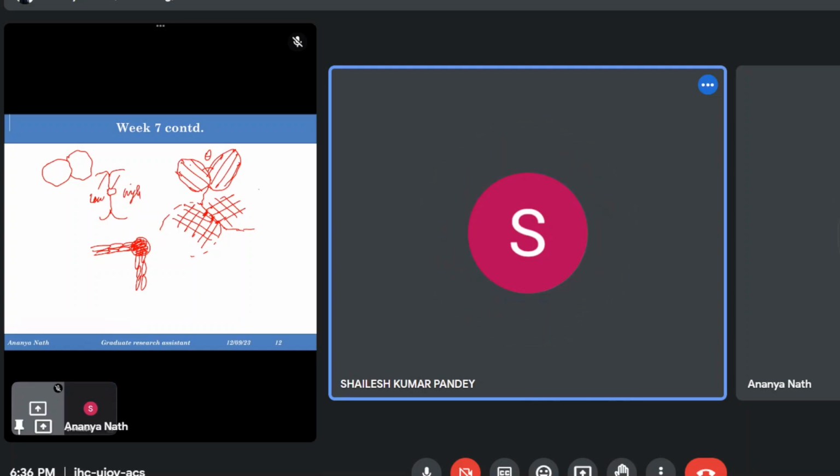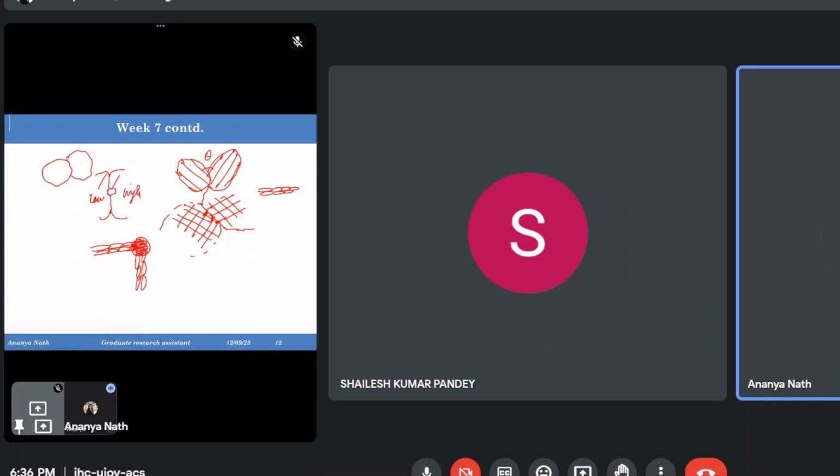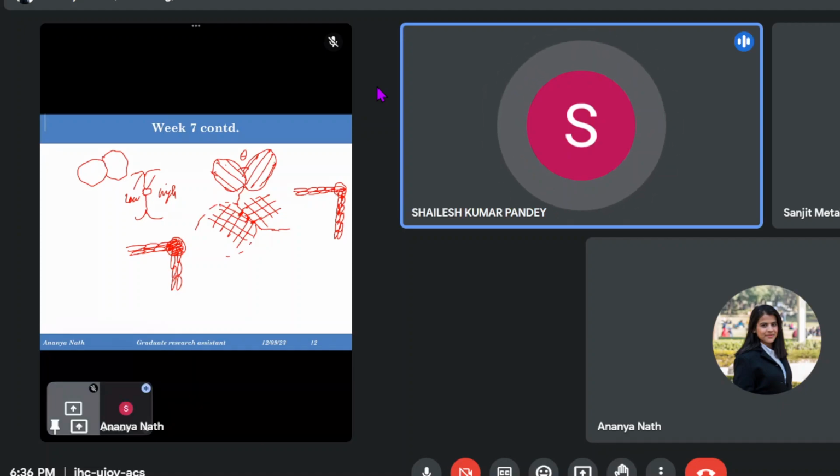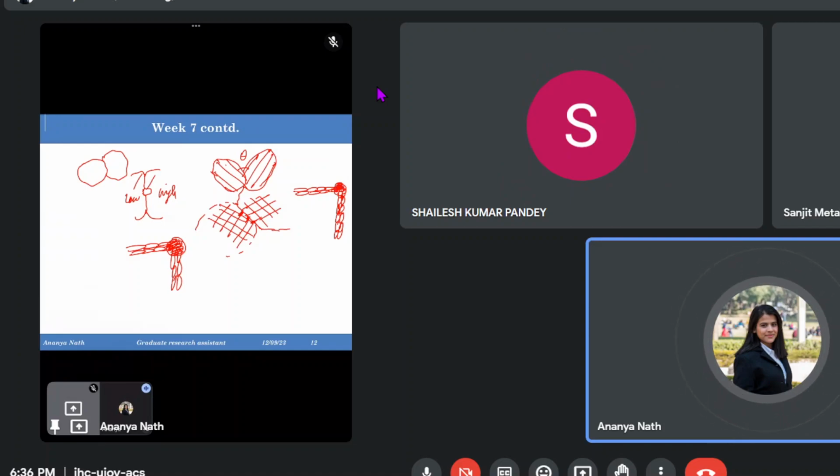Yes. These columnar grains are low angle because they are oriented in a similar direction. These columnar grains are again oriented in a particular direction, so they are low angle. But when these two columnars interact with each other, they make some high angle zone. Out of that high angle zone, you will get some grain refinement by the high angle boundary region. But it's not always true that you'll get equiaxed grains very easily. Means, ma'am, we can say in between we are getting a low energy configuration? No, no, this interaction will give rise to a high energy boundary.